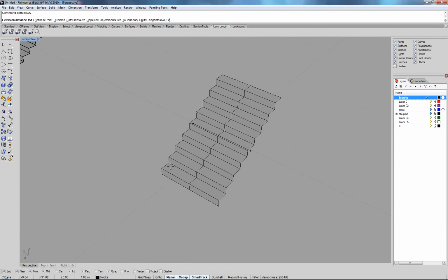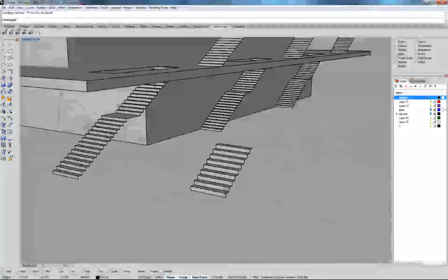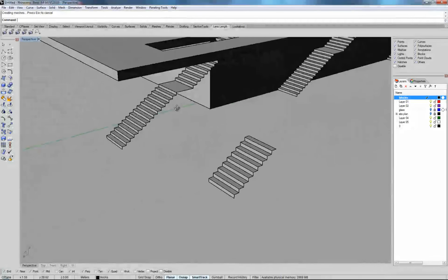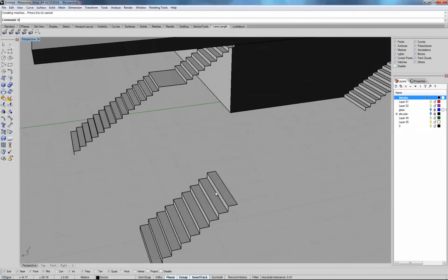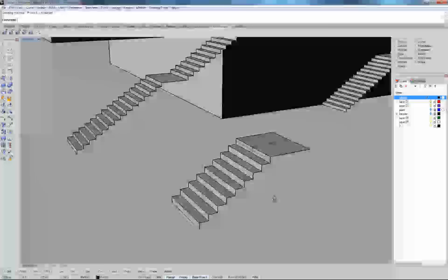After that, I simply have to do Extrude, select width, let's say 2 meters, and here I have my stairs. And eventually when I get to a point where I have to have a landing, I can just say Move Edge, click it, and then move my edge, Tab key, so it gets locked, sorry, and I can just say 1.2 meters, and there it is.